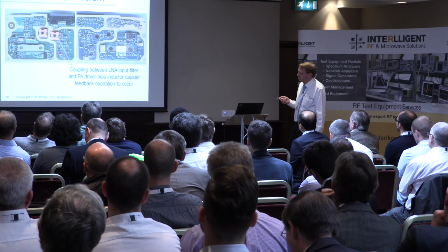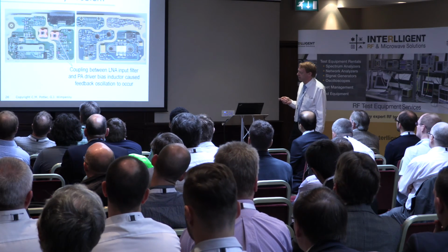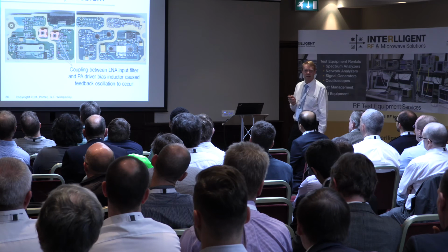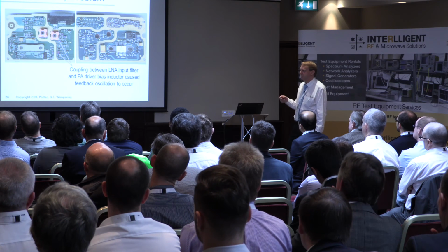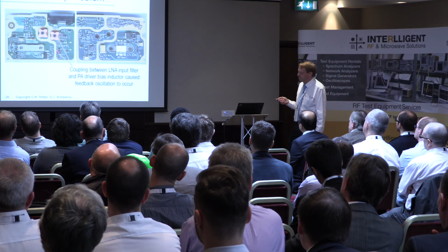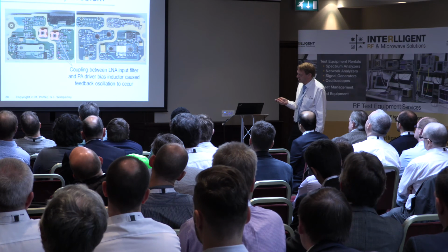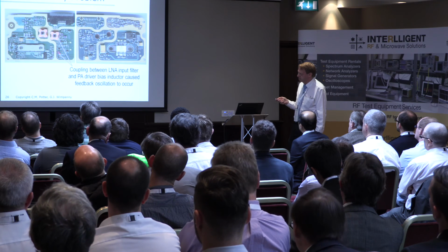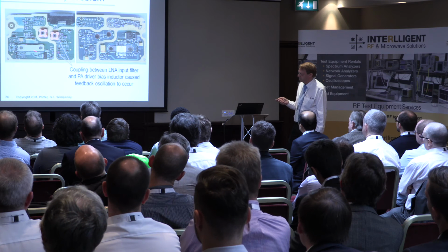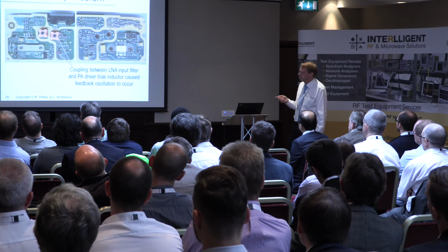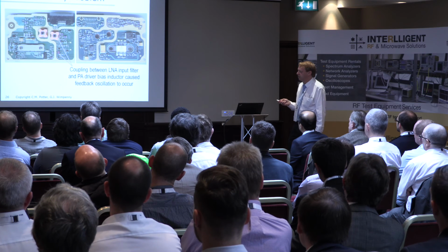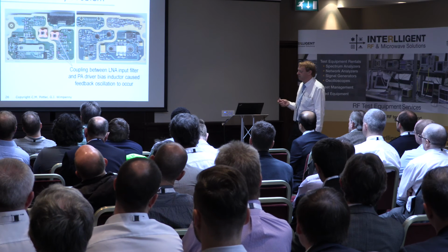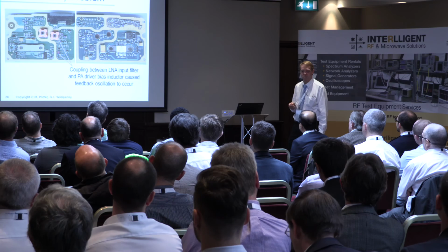And it turns out that there was a kind of feedback loop going on here, and as you can see from the bullet point, the radiation from this inductor here, which is part of the LNA filter, was actually magnetically coupled enough to this biasing inductor down here, which is on an earlier stage of the amplifier. There's a little RF transistor down there that this is biasing. So signal gets through that amplifier stage, through that one to the output one, and actually enough leaks through the isolation of the transmit-receive switch to feed a little bit of signal through the front-end filter of the receiver, completing a loop which hadn't been foreseen.